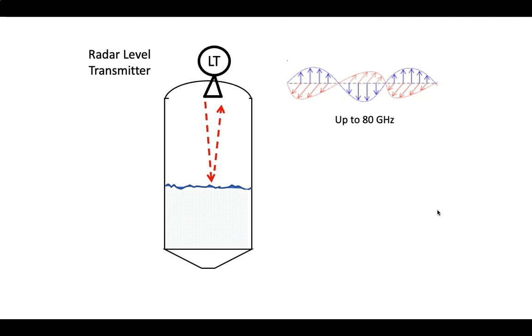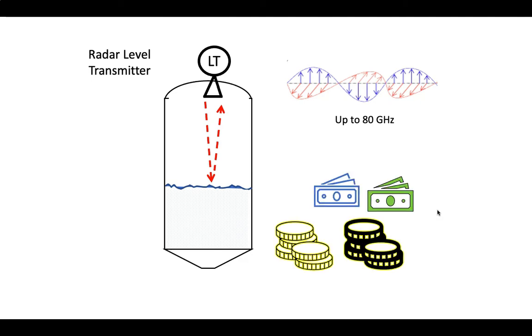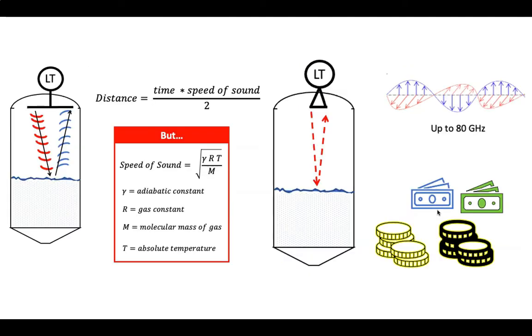However, you must know that the disadvantage of using that radar level transmitter is that the cost might be more than using an ultrasonic level transmitter. So those are the things that you should be looking at when it comes to advantages and disadvantages. Also mention things like reliability, accuracy, maintenance in terms of the maintenance package of that particular instrument. That also plays a role. Also, if the instrument works very well but the technology is very complicated for the people in the plant, then that can also be a disadvantage for you.